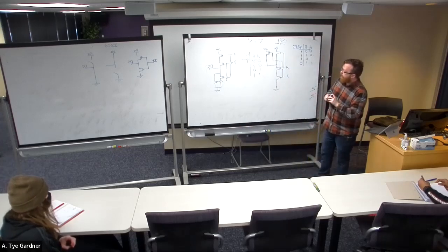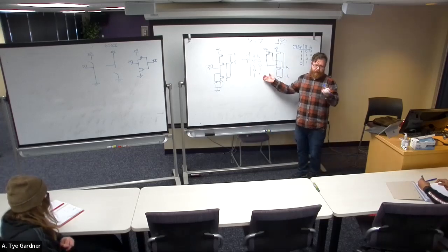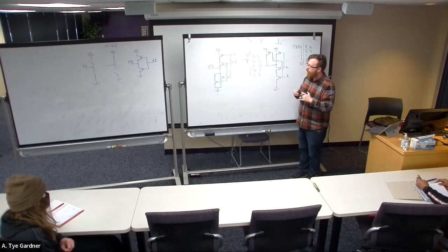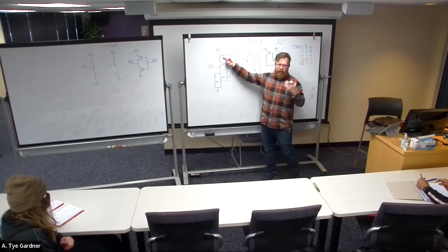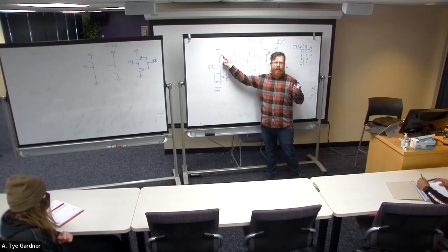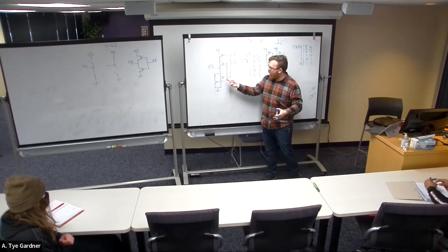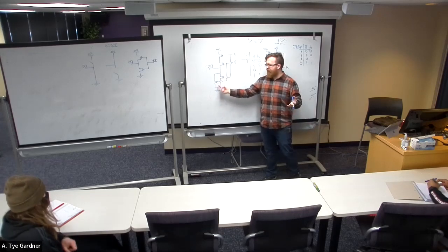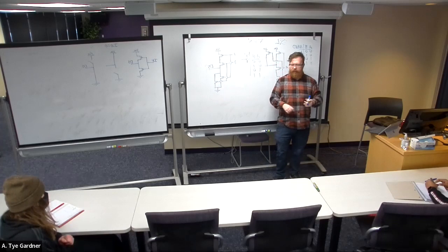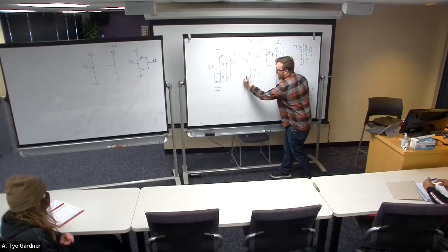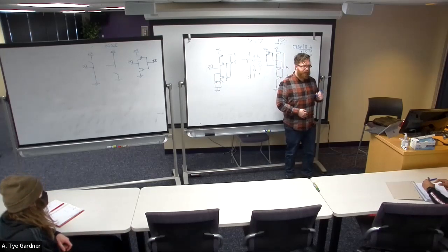All right. Let's do the 1-1, because the 1-1 is the other easy situation. Well, that means both of those are off because they're inverted, right? That's what the bubble says to us: if there's a 1, it's inverted to a 0, 0 being off. That's kind of what it's telling us. Well, a 1 here makes that connection, it turns it on. A 1 here makes that connection, it turns it on. They are both pulling to 0, therefore it's doubly a 0.